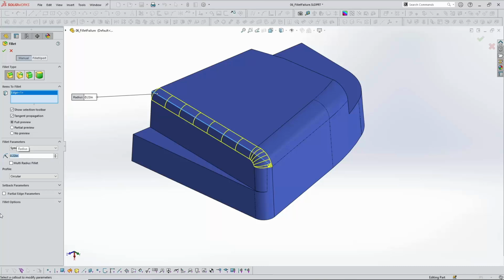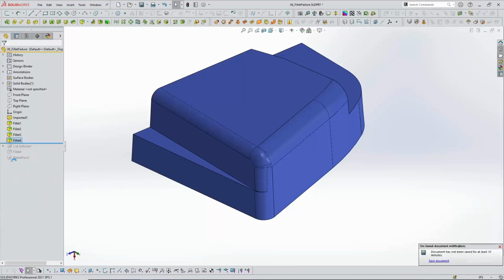Oh, there's the preview. This is looking pretty good, right? Well, if I'm not putting in a dimension on it and it's in the block tolerance, does it really matter? I get my job done, I go home at the end of the day. Who's going to know other than me, especially when I step this out, right? That it wasn't a 1/4 inch fillet. So we're going to remove that fillet because we actually want to do the best possible job here. We want to make sure that it is that true 1/4 inch.